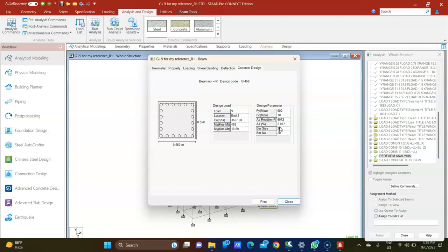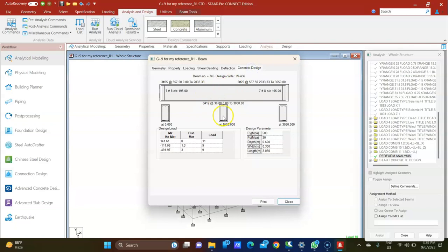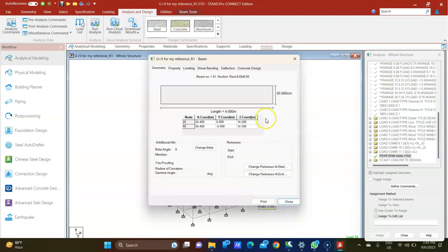Okay, I am showing you one beam also. Yes. That is the section, right? You need to see this one. Longitudinal sections, and they have given 3 cross sections. Fine? Yes, they have given 7 numbers of 8 phi at the rate of 1. They have given it. In the case of column, they have also given it.